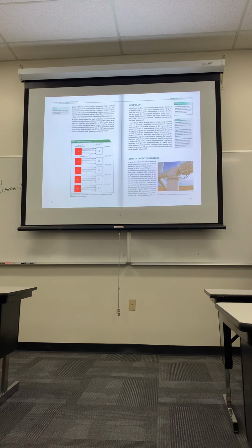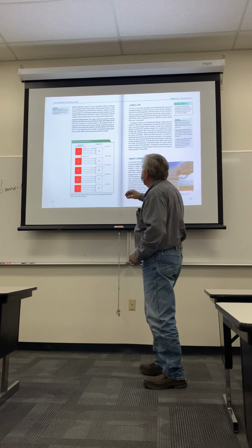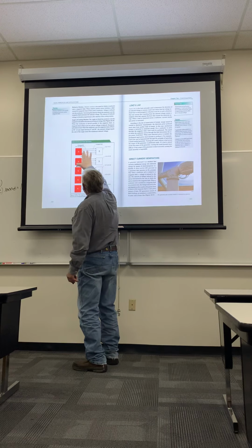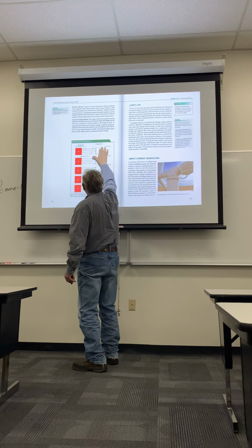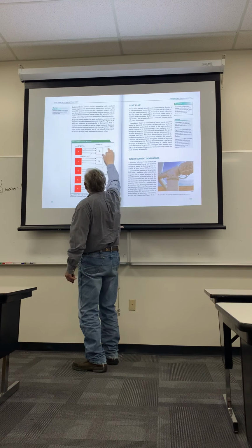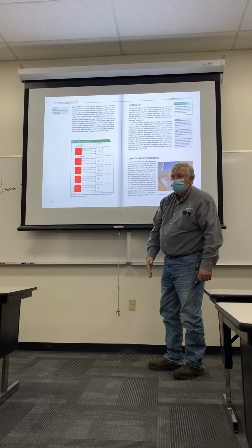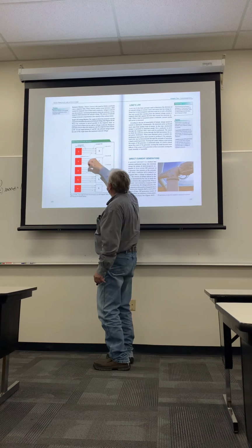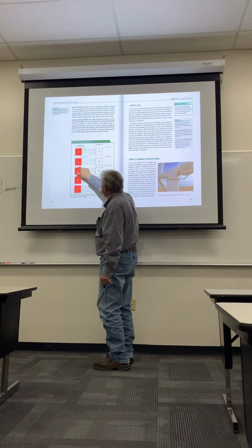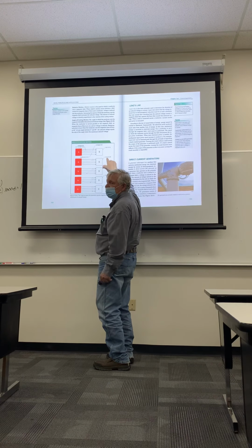Which gets us to this next really useful thing, which is the angle at which a conductor cuts through a magnetic field. So here we have a north and a south pole, and we have some lines of flux in this magnetic field, and we're passing a conductor. If we move this conductor back and forth this way, you're going to produce no volts, because you're not cutting through the lines of magnetic flux. But if we angle that a little bit, at 30 degrees, and we move that conductor this way, now we're starting to cut those lines of flux, and we get about a half a volt